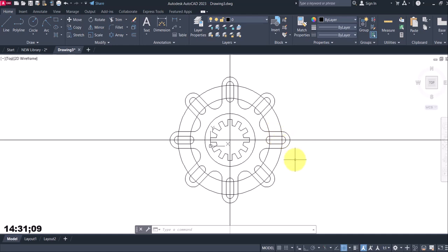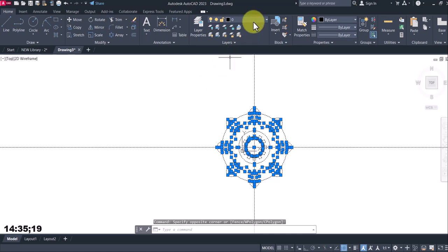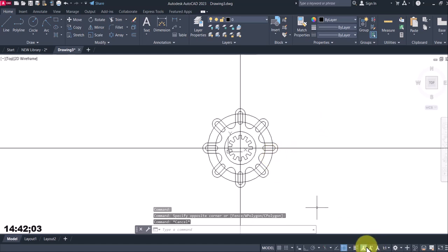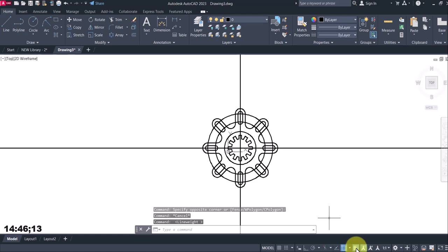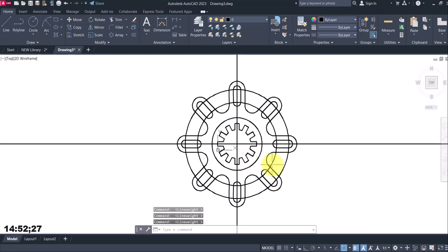Now I'm going to apply my property. So I'll first select everything and group everything under tick. Escape. So the tick lines are not showing. I can activate show or hide line width, one of the drawing aids here, to make my line width visible.